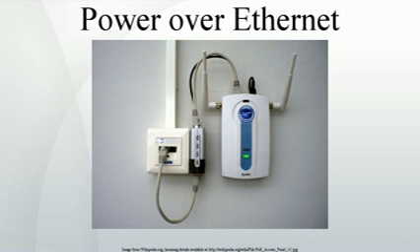Power capacity limits. Category 5 cable uses 24 AWG conductors, which can safely carry 360 mA at 50V according to the latest TIA ruling. The cable has 8 conductors, only half of which are used for power, and therefore the absolute maximum power transmitted using direct current is 50V x 0.360 A x 2 equals 36 W. Considering the voltage drop after 100 m, a PD would be able to receive 31.6 W.